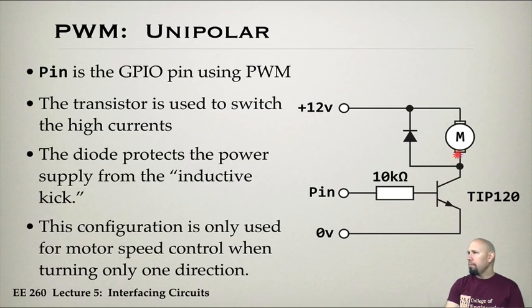That's how this works. This is a 12-volt DC motor, and the transistor again handles a higher current than the Arduino can handle. The current that comes out of this goes through a 10K resistor and then to ground, so there's not much resistance that this pin is going to see from this circuit. It's going to see at least 10K of resistance, and that's not a lot.